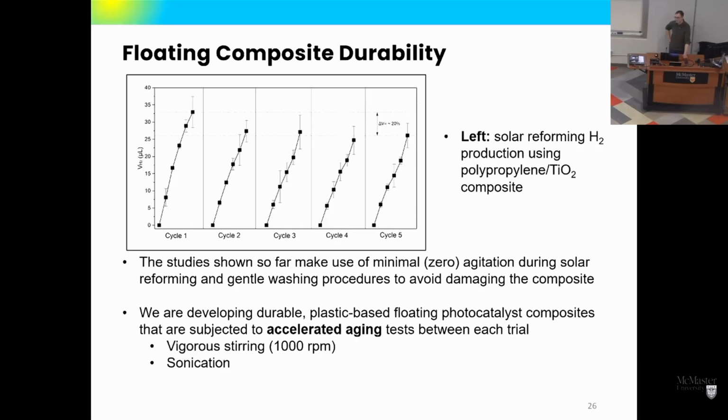So yes, when we're dealing with mixed waste streams, it becomes a lot more complicated. And not just materials that can't be easily oxidized, we also have materials that might foul the surface of the catalyst or poison the catalyst. One of the growing pains we went through with H2 Nano was working with a whole lot of different industrial waste streams and trying to find ones that worked for the process. So that's something we're going to have to target with our pre-treatment processes. We're going to start with as pure substrate streams as possible, then work towards mixed wastes and try to figure out where the problems lie.